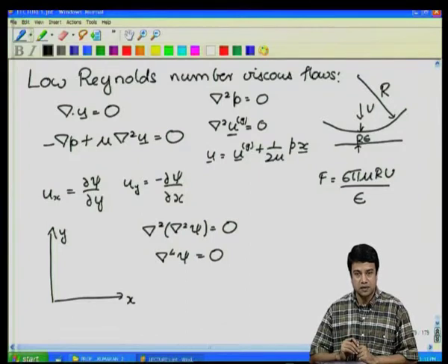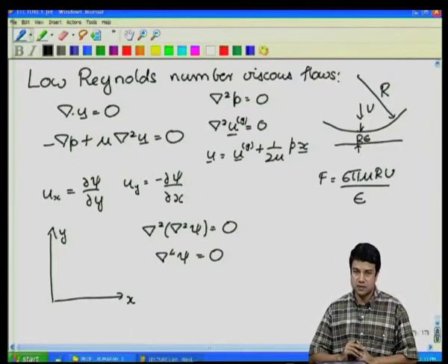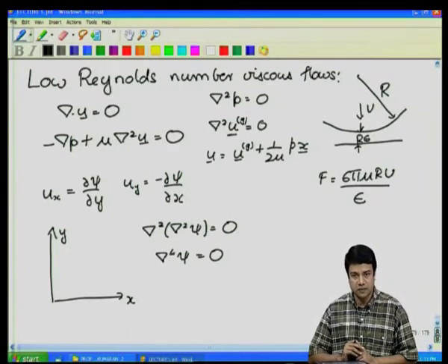There is one further little bit that we need to do, and that is when we solved the Stokes' flow equations, we assumed that the convective effects could be neglected everywhere in the fluid. That is, diffusion is dominant. Diffusion is dominant means that the momentum diffuses instantaneously throughout the entire domain. Okay. However, the domain is infinite in extent. If you take, for example, the flow around a spherical object, can the momentum really diffuse everywhere instantaneously when the domain itself is infinite in extent?